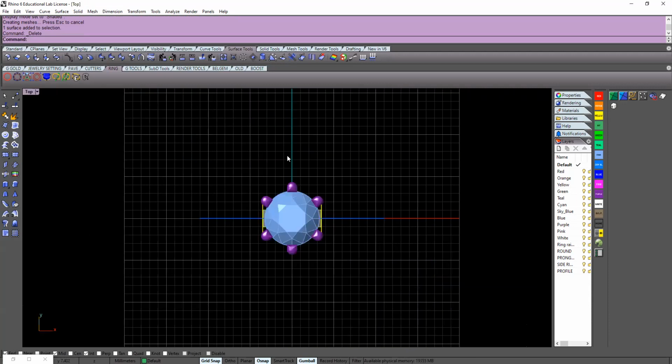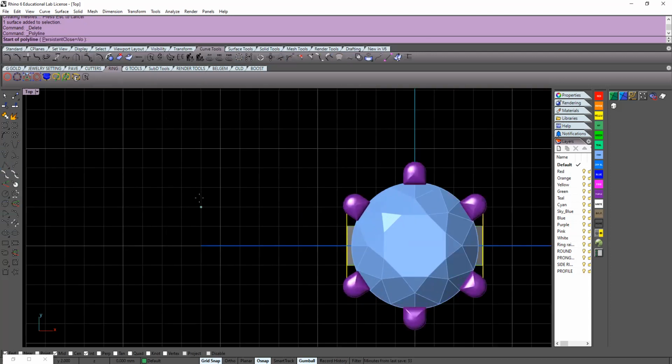When I draw curves, I like to do them in the top view. It's not necessary, but that's just where I like to keep them. Okay. Curve tab, line tool. We can also do polyline. So line creates one segment. Polyline creates new lines where the last one ended. So this is probably better for us.